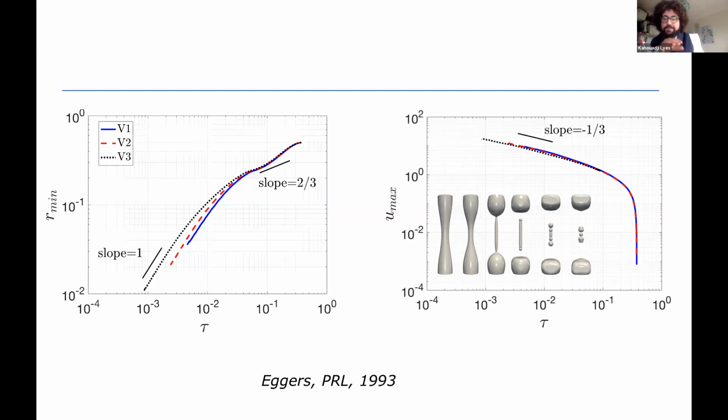You have a CFL time step, the capillary time step, the diffusivity time step. I think we have something like 6 or 7, and we select the minimum of all of them. If the flow is dominated by capillary breakup, the interfacial CFL will dominate, and all those types of singularities will be handled accurately. No problem at all. This is validated.